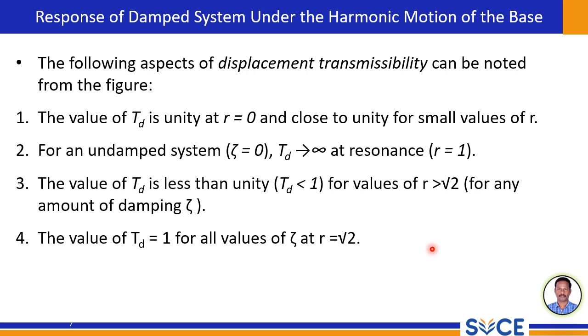This means at this specific frequency, the mass vibration amplitude is exactly the same as the base motion amplitude, irrespective of any damping in the system.